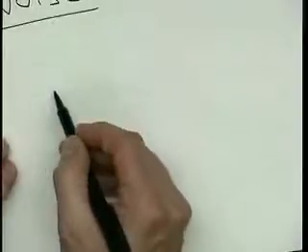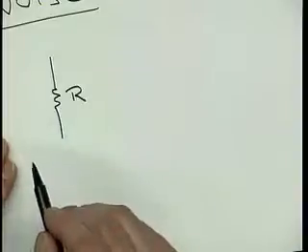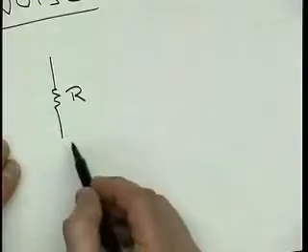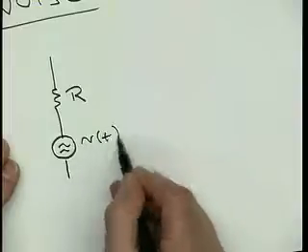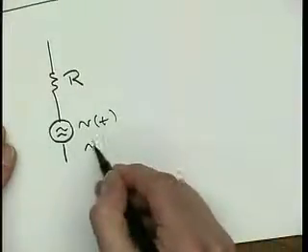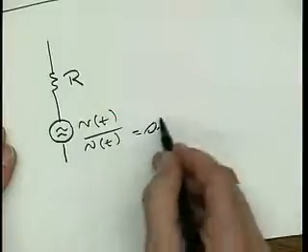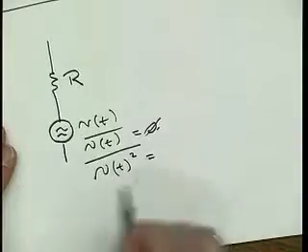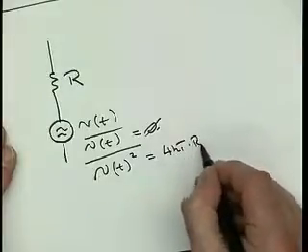We can model a resistor by its noise voltage. Again, we could use sort of what they do with operational amplifiers. We have here the value of the resistor, and we could say this is sort of like an old normal resistor, none of this noise business. We model the noise with a series voltage source, and we don't know the value of its noise source. All we know is that its average over a long enough time is 0, right? And we know also that V of t squared over a long enough time is going to be 4kT times R times B, right?